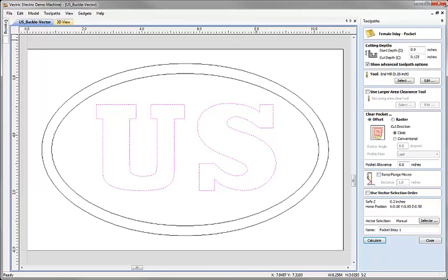Because the software's automatically accounting for the radius of the tool, if I don't do that, then the two parts won't fit together correctly. In addition, the pocket allowance allows me to specify an extra distance which will give me a little bit of play between my two parts. If I don't put any allowance on it at all, then it will be too tight a fit for my parts to go together. That pocket allowance can also be used to allow for any finish you might be adding to the part which might give it additional thickness, such as a paint.